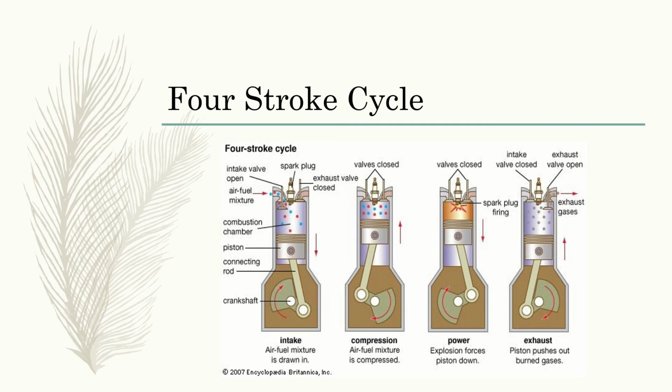Then the next 180 degrees is the compression. In this stroke, the piston compresses the air-fuel mixture in preparation for ignition. Both the intake and exhaust valves are closed during this stage. So we have completed a 360, so the crankshaft has made one revolution.